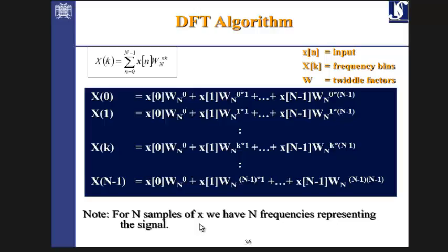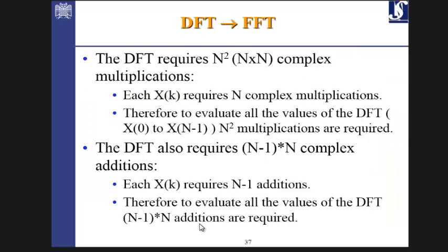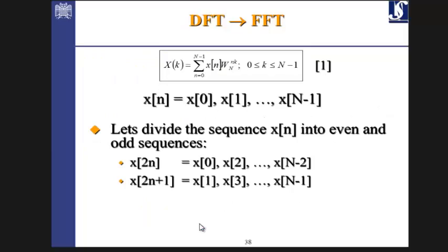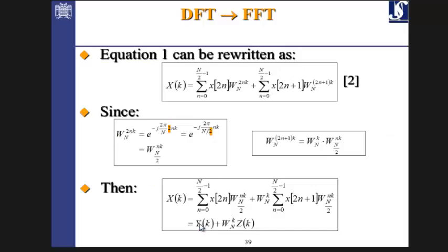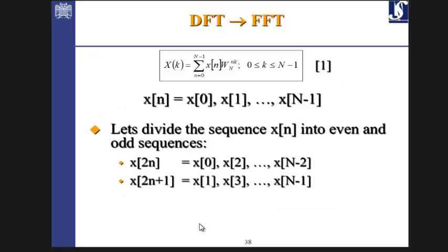So for FFT, just to know what they actually did, they used the idea of periodicity of the eigenfunctions. So this W_N as the eigenfunctions, if you look at these eigenfunctions more carefully, you see that they can be divided into two different sequences, one of them even and the other one odd.